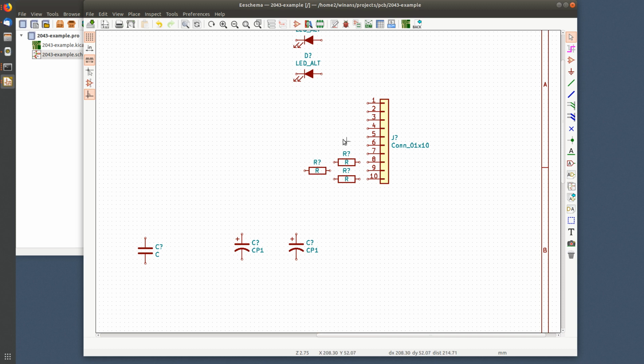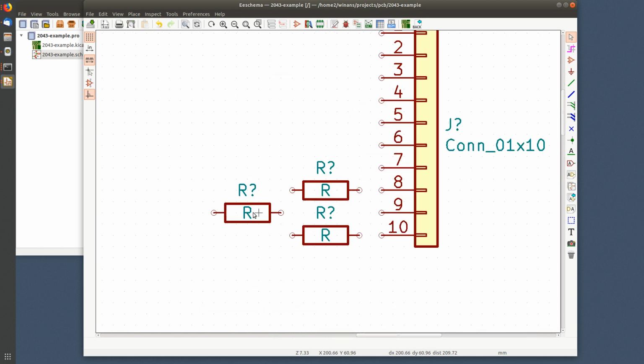Now that I've rearranged these symbols on this resistor, if I type C to copy it, it copies it with the rearranged values too, which is pretty handy. These guys, once you get them arranged, you can start cloning them like crazy. Now, even as it's drawn right here, if I connect a wire through here, I will be running it through the notation, the value, the enumeration of this. So sometimes I might move these over to the side like this. If you really need high density stuff, this sort of thing helps a lot. Okay, now I can connect all these wires up without going through these names. And maybe I want to move it over to the left.